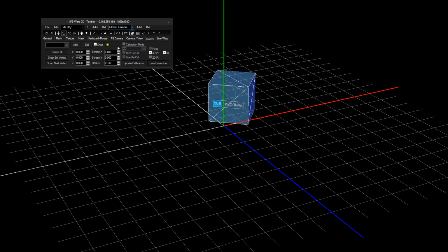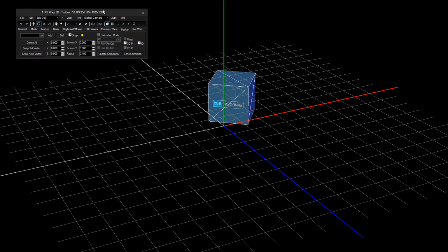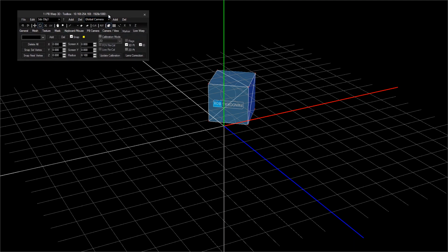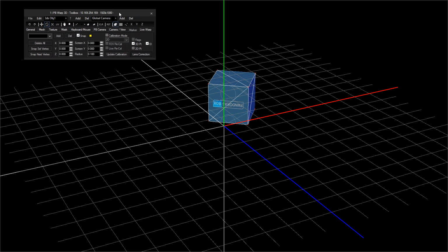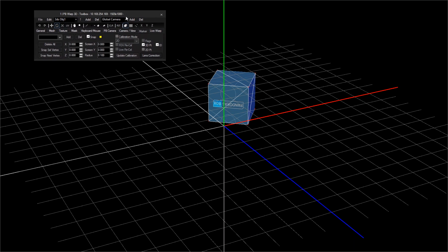Any questions to this? Nothing so far, but I just wanted to repeat the point. Pandora does not take the pivot point. It always sets it to 0, 0. So whatever you have set up in your 3D file, it's ignoring this as well. This is just because if you have many objects and you want to import them as a venue site, they all rotate around one point when you rotate your scene or your layers in that case. That's the reason why. So we just wanted to point out that there are two differences in both programs.